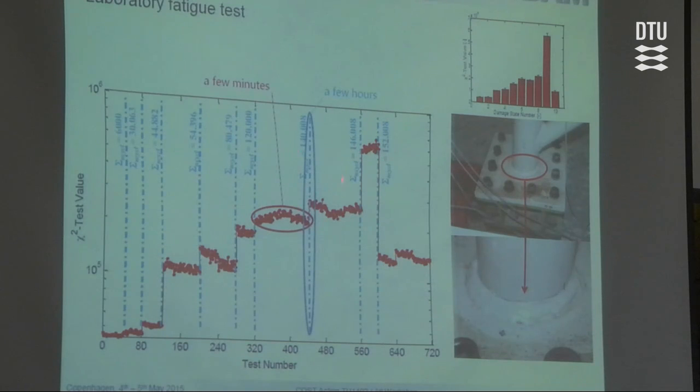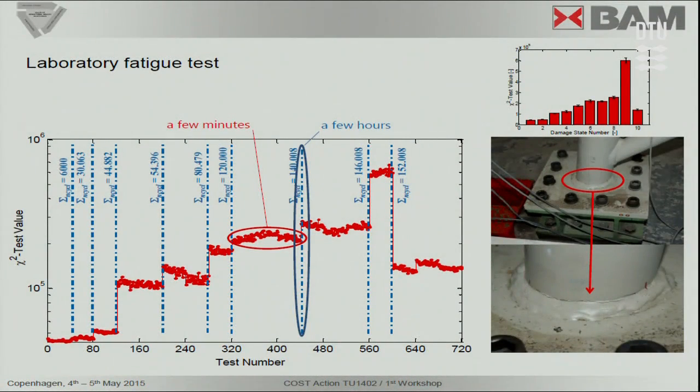and the indicator increased, so we could see that the damage increased, and then it dropped down after another 6,000 load cycles, I think. The reason was that a second crack occurred in the second leg, and the vibrational characteristic is then more different from the reference state, so the indicator dropped down. The diagram up here shows the mean values of all the load stages in these bars.